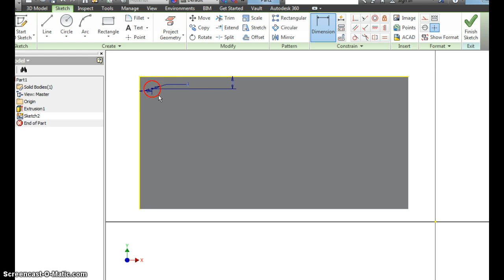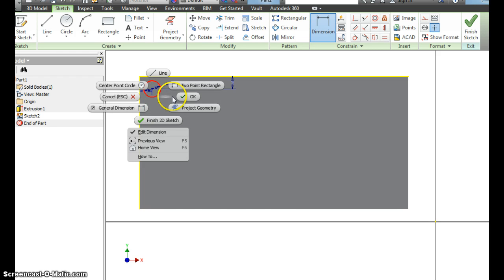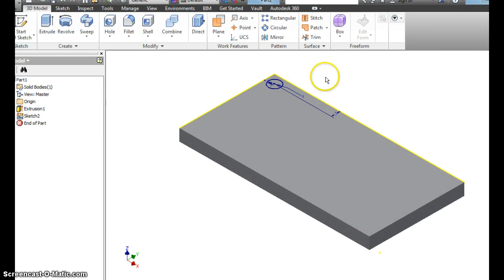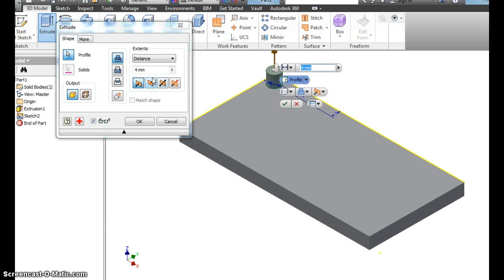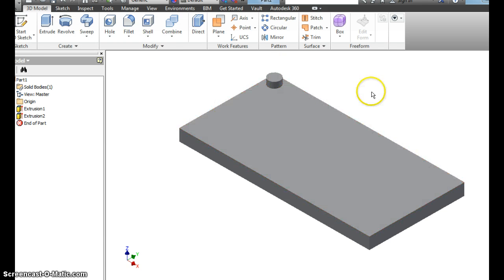circle. We're making an 8x4 piece, so we're going to have 32 circles on the top eventually. But instead of doing 32 separate sketches, we're going to use the pattern tool. So right click, finish 2D sketch. We could do a 2D pattern and extrude them, but it's easier. We're going to just extrude that one circle. Make it pop up. We want it to be sticking up. Let's see that. 2 millimeters looks good. So hit OK. So now we've got one circle.